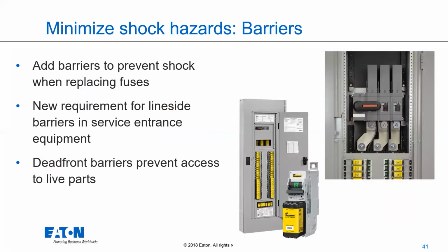Barriers are also a great way to minimize your shock hazard, right? Add the barriers, particularly when you're replacing fuses. There is a new requirement for line side barriers in service entrance equipment, right? So there should be line side barriers in your service entrance equipment. And this makes sense, right?